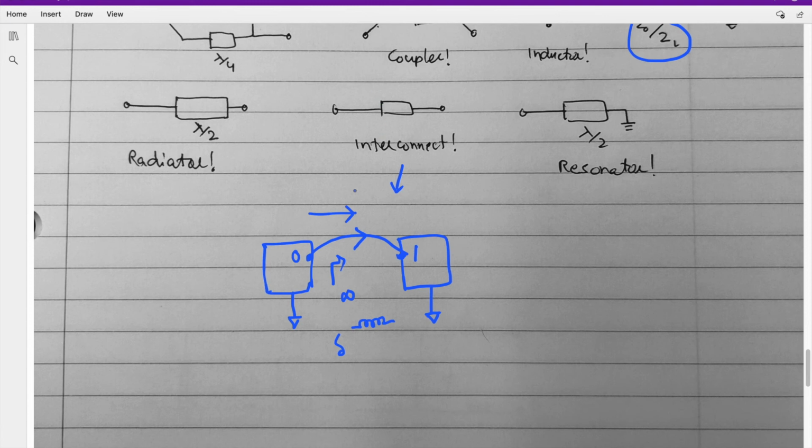That is why we have to consider a transmission line. That is why you have to take care of the ground path as well, so that if this thing has some inductance, it also sees capacitance with this path. In other words, it forms the same LC section that we have been talking about, and it gives us a constant impedance of 50 ohms, or whatever characteristic impedance you are designing it for.